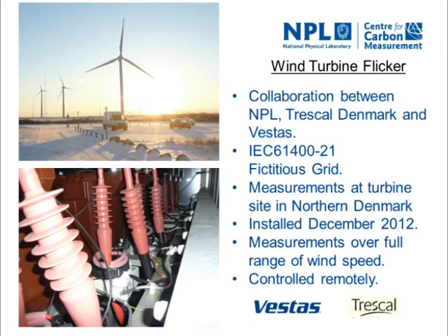such that we can characterize these wind turbines for Vestas such that they can meet this IEC standard that I've listed there, which uses this very curious term called a fictitious grid, which allows you to make various adjustments to your measurements to take into account the impedance of the network at various points where the wind turbines are connected. And again, down the bottom there's a picture of our Rogowski coils installed on this wind turbine installation.